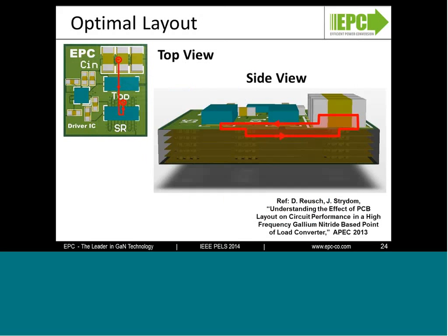And when you look at these applications, especially as we can continue to shrink the figures of merit and we continue to increase the switching speed, figure of merit isn't the only contributor to loss. We find that it's also very important to have a low parasitic package. And as Alex showed our devices earlier, we have an ultra-low parasitic chip scale packaging that's accomplished because we're a lateral device. All of our connections are on a single side of the device.